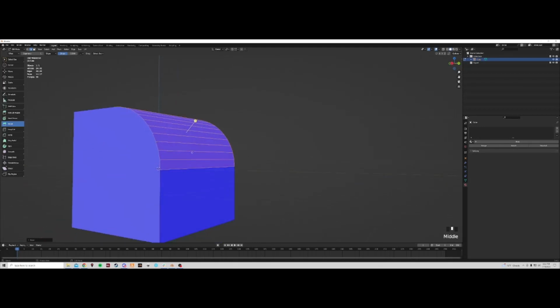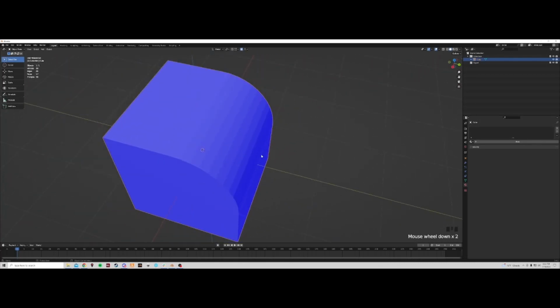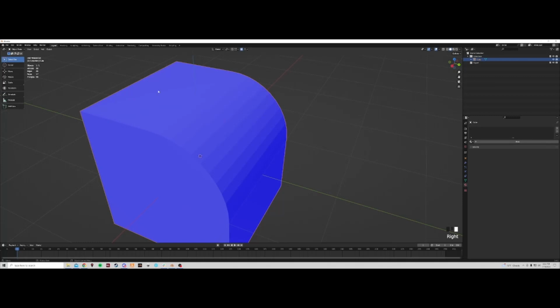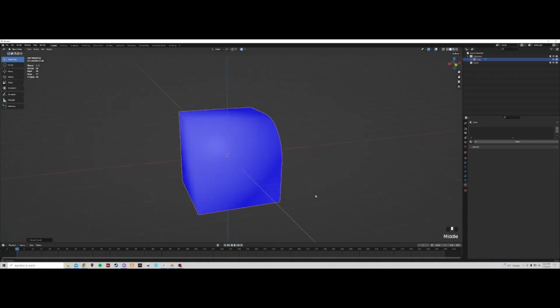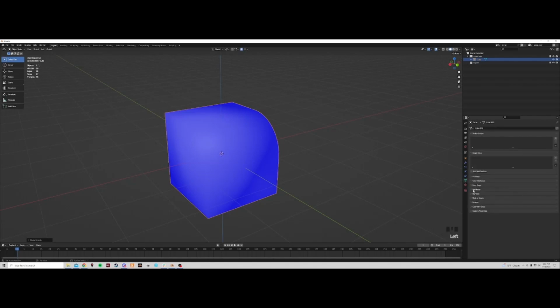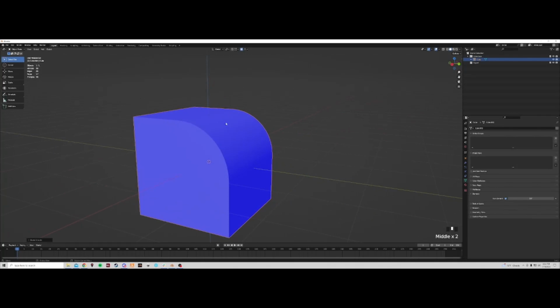Be careful about how many faces you have. Where this looks blurry, or like you can see the edges and it's kind of ugly, if you right click on this in object mode and choose shade smooth, that gets blended. But right now, your sharp edges are blended too. We still want these to be sharp. We can actually go to this little green tool here. That is, this object has data that is stored for it. This is the data property. Under normals, you can auto smooth. Now you have sharp edges. You have not sharp edges. This is a smooth edge, right?